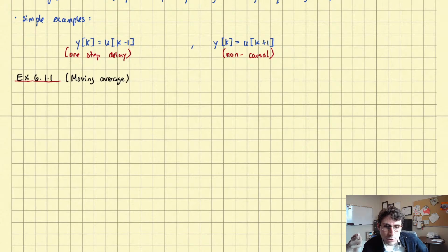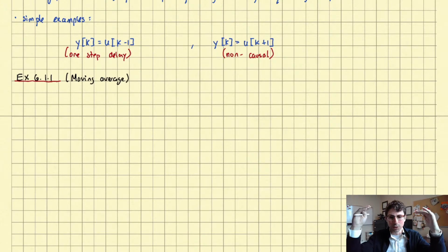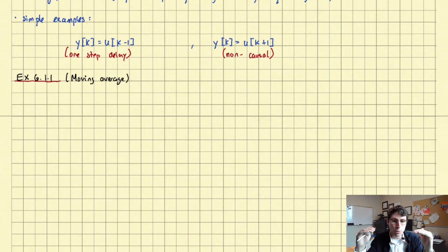one way to get around the issue of not having future information is that you take all the information you have up till now. Remember feedback control: sense, compute, actuate. You sense, you try to get a feeling of the state of the world right now. At the computation stage, what you could try to do is predict the future. But it's a prediction. You're not using real information about the future. That's called model predictive control, or MPC.